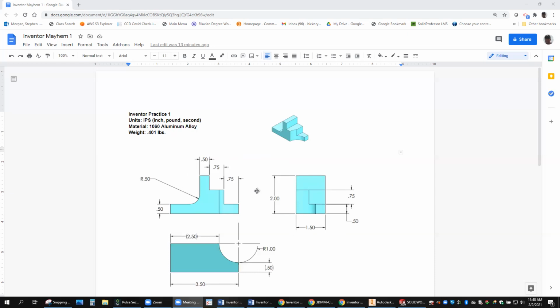It's not just half an inch, it's quite a big jump. Your sketches tend to freak out, and you get warnings because constraints are broken or something weird. A lot of the time I end up just starting over, and that's not something you want to do. So when you first set up your document, make sure you're in the correct units.